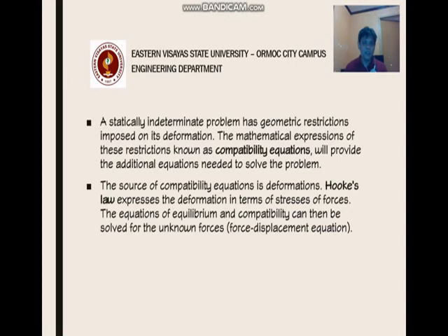And these additional equations are known as the compatibility equations. So together with the equilibrium equations, plus these compatibility equations, you will now be able to solve statically indeterminate problems. Now, the source of compatibility equations is deformations.